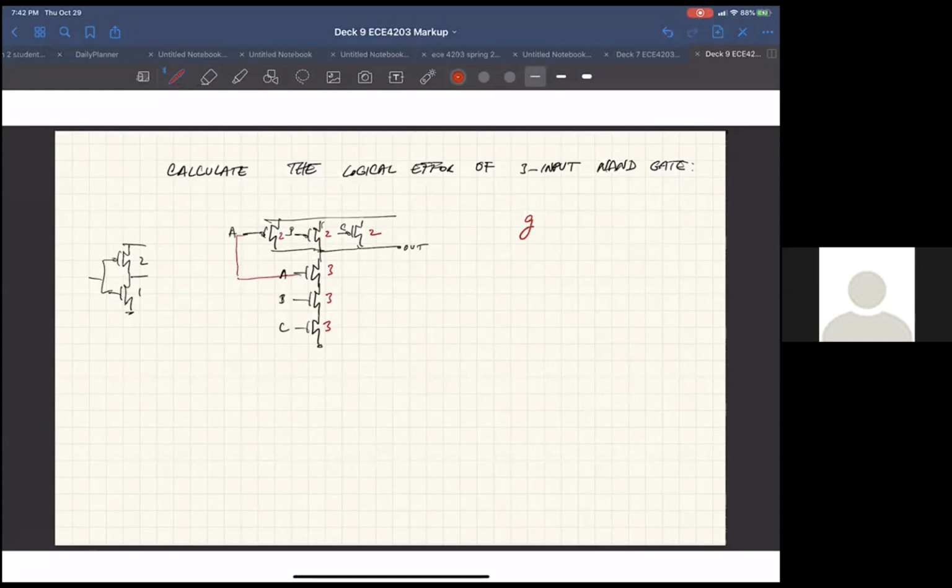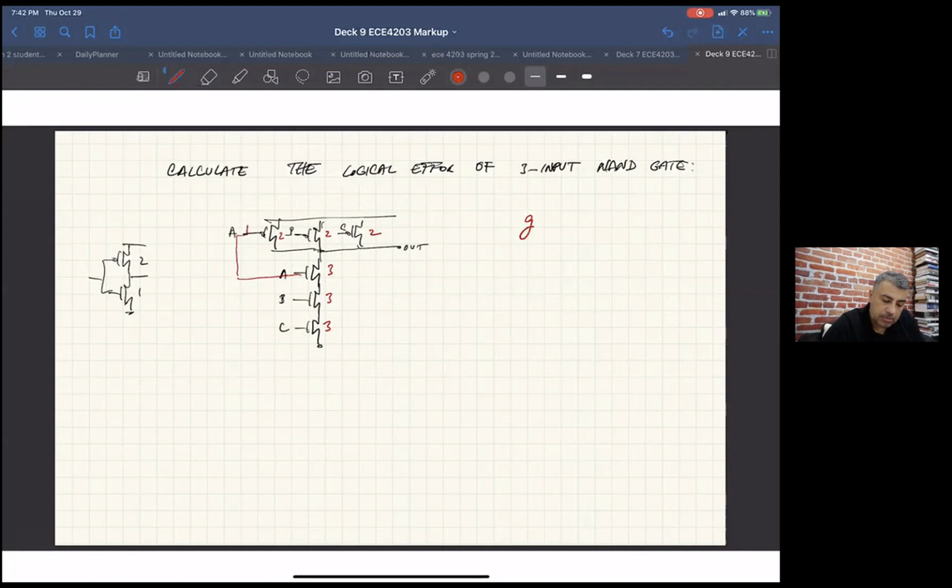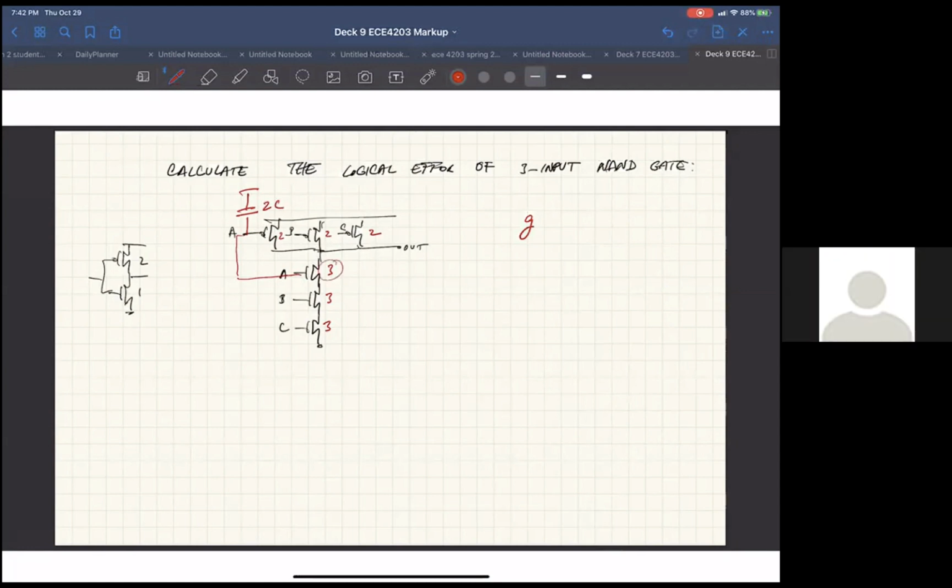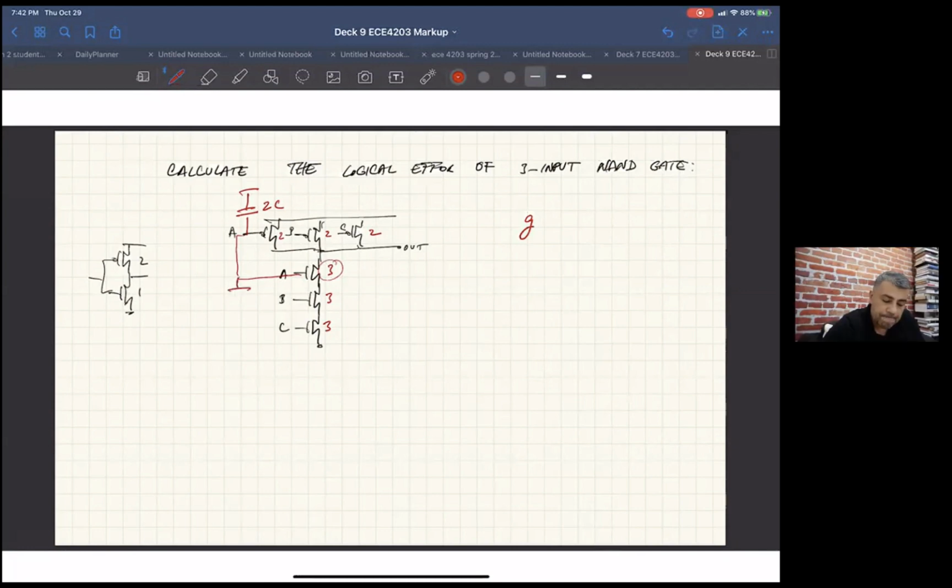Okay. And you start counting up capacitances. So this input for the P MOSFETs, what's the capacitance you'll have? Would it be 2C, right? Yep, it'll be 2C, this guy. And for the N MOSFET, it'd be 1C. Remember you made this 3x. Oh, right. So it'd be 3C then, right? 3C, yep. So in total, this guy is 5C.